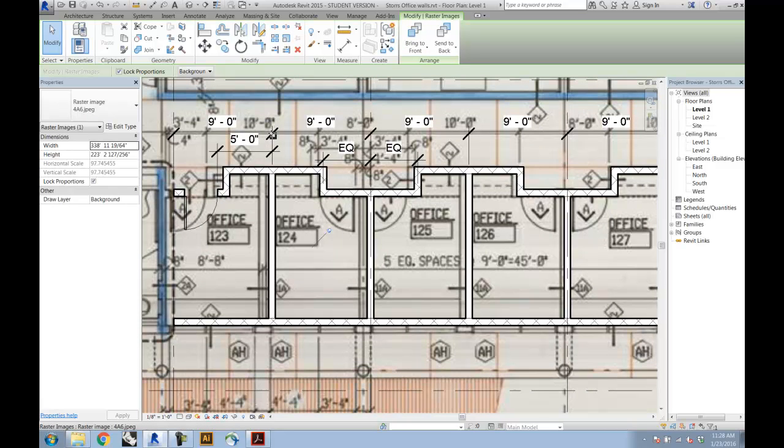Same thing here. So we've got this 8-foot dimension from this line that comes out to the edge of the wall, and the door, it looks like that's 8 inches. The door is 3'4", including the frame. So that's going to mean that 4 foot minus 3'4" would mean it's 8 inches from the center line of this edge.